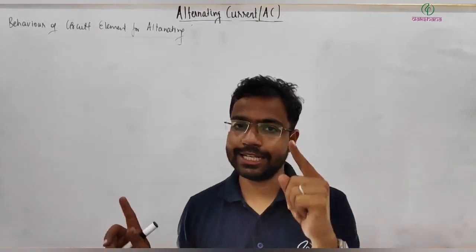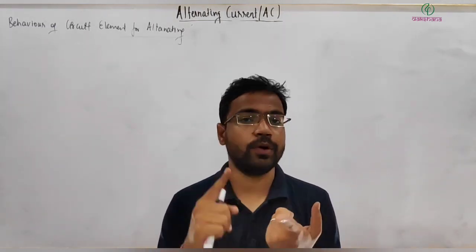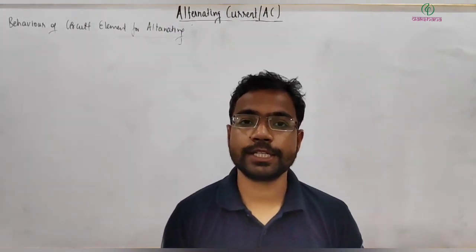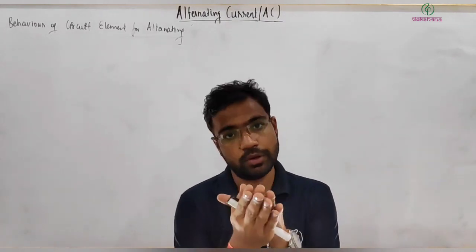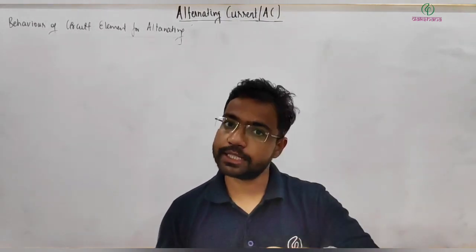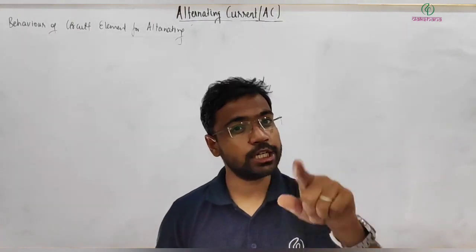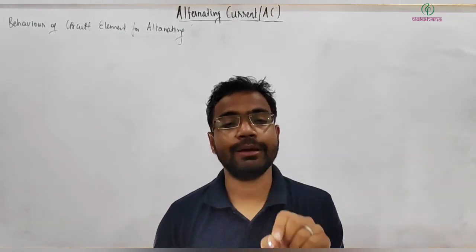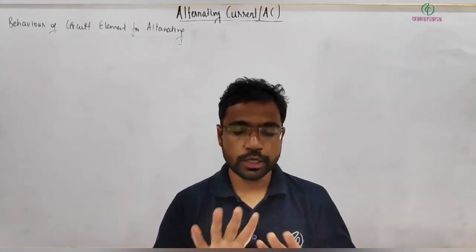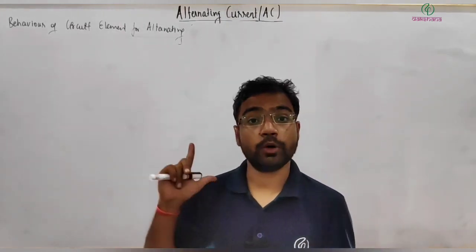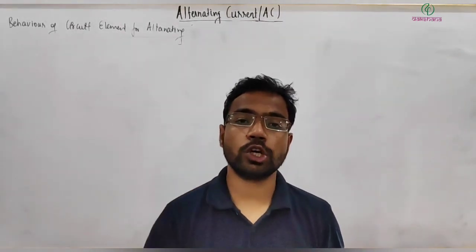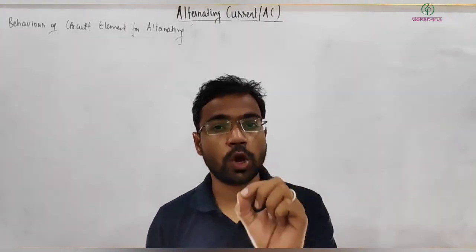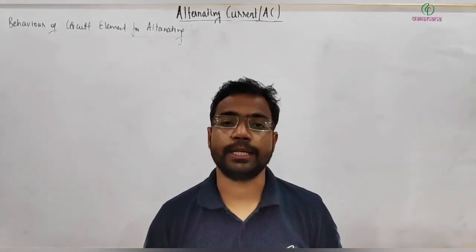Remember, this is very important: in the phasor diagram for a purely resistive circuit, both are in the same phase, right? One point. In a capacitive circuit, your EMF lags. In an inductive circuit, your EMF or potential difference leads current by pi by 2. In a capacitive circuit, potential difference or voltage or EMF lags current by pi by 2. So that is another important point about the phasor diagram. I told you, in the case of series, we will try to draw on the x-axis the quantity which is common or constant to all the elements, right?